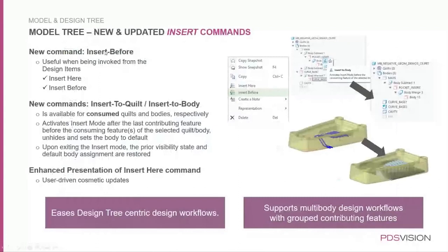Then, while we have these multiple trees, we now have new and updated insert commands as well. Before we had just an insert here, which simply means that after the selected feature, put the location in there and insert my new feature. Now we have an insert before as well, so not after, but just before it.